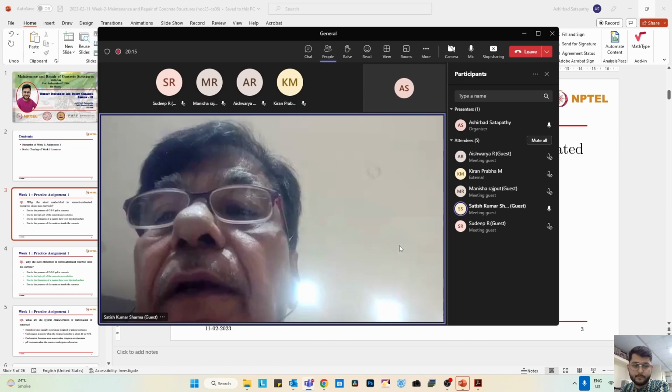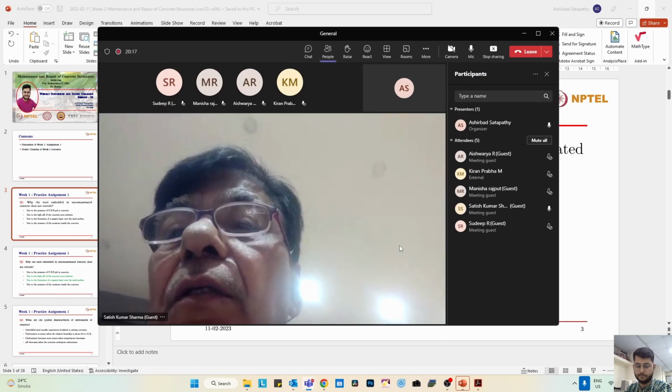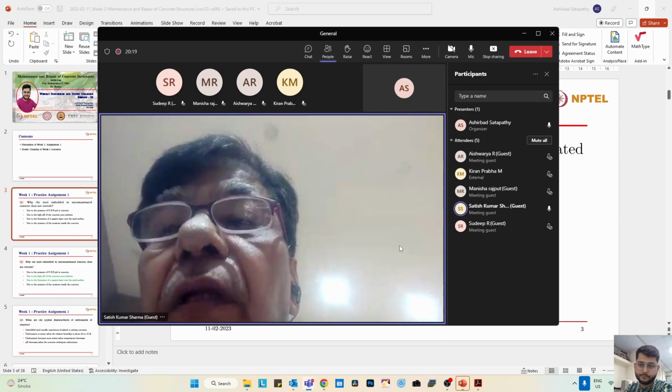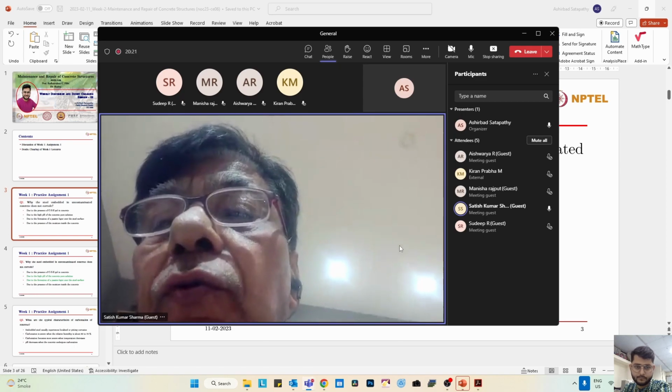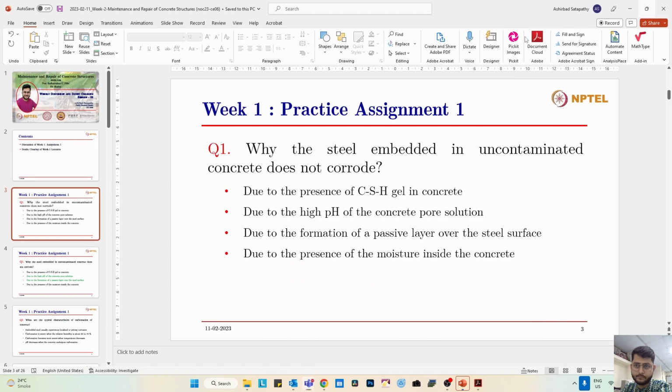Am I audible? Yes, yes, Dr. Satish. Answers are two. Firstly, due to the high pH of concrete pore solution, which is of the order of 12.5, 13 or so. And the second reason is due to the formation of a thin passive layer over the steel surface.